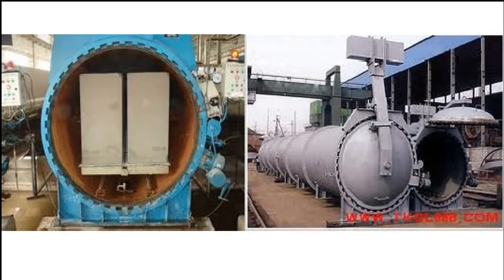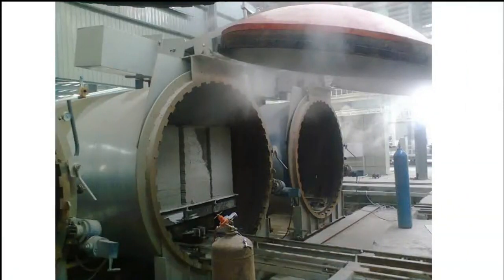These are the chambers in which you put the concrete members to subject them to steam at high temperatures. So we cannot just use some polythene sheets, right? You are going to put them in this closed chamber, and this right side image shows the cover to it. You are going to cover it, and you are going to supply the heat at the particular temperature, and the proper steam pressure is going to be maintained. And these are the chambers. See here, these are the deep beams or girders, reinforced concrete beams, which are being steam cured.